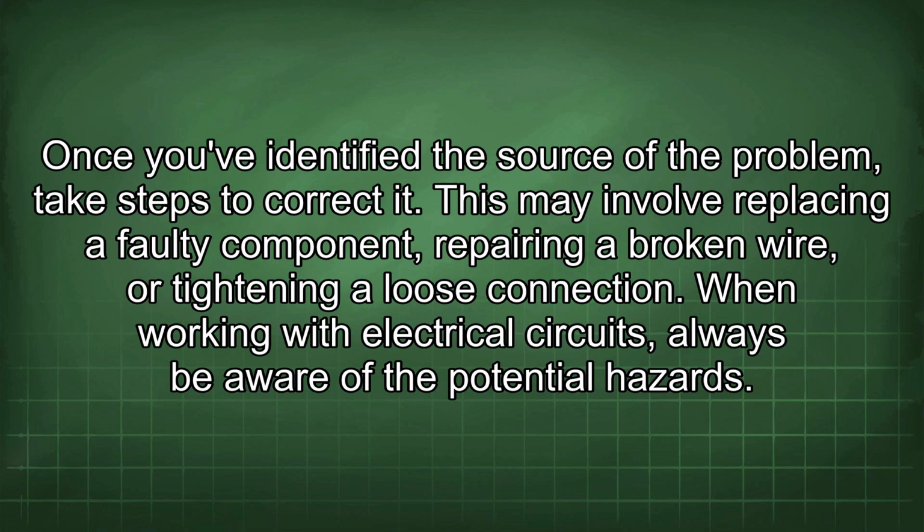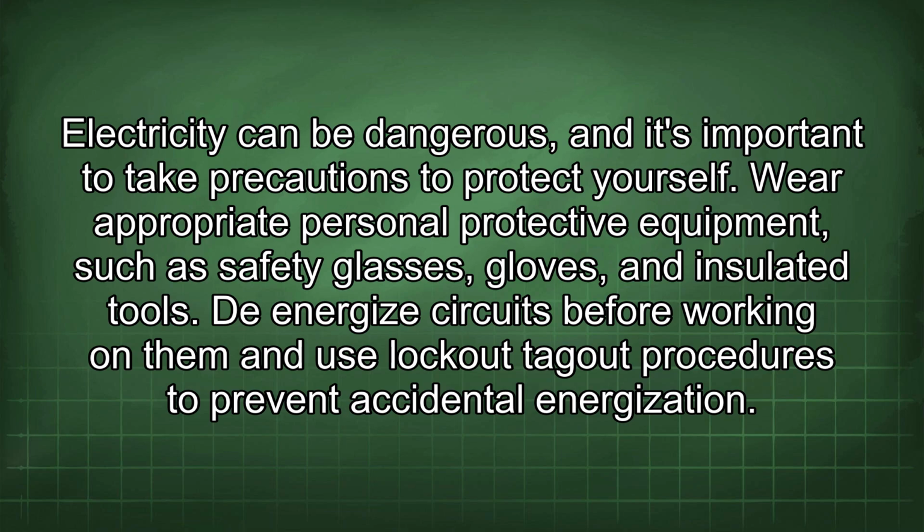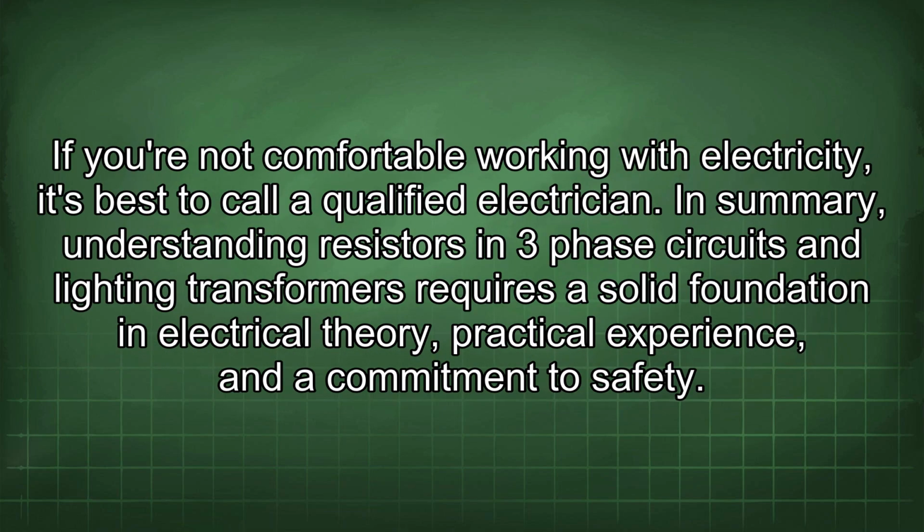When working with electrical circuits, always be aware of the potential hazards. Electricity can be dangerous, and it's important to take precautions to protect yourself. Wear appropriate personal protective equipment such as safety glasses, gloves, and insulated tools. De-energize circuits before working on them and use lockout-tagout procedures to prevent accidental energization. If you're not comfortable working with electricity, it's best to call a qualified electrician.